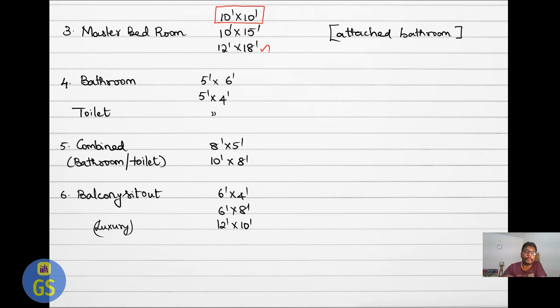The next, we want to have an individual bathroom. So we want a detached bathroom, without anything inside the room, so it's a dedicated bathroom, a dedicated detached part. So there we need to know how much size is required. When you prepare this bathroom, this is a very critical part in the planning, because we need to have a spacious area for taking a bath and toilet. So make sure that your dimension should not be less than 5 feet by 4 feet or 5 feet by 6 feet. So this is a basic size when you do planning for a bathroom and toilet.